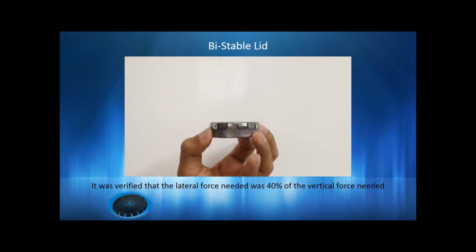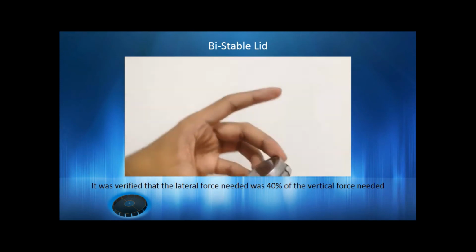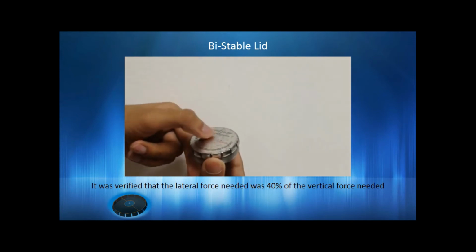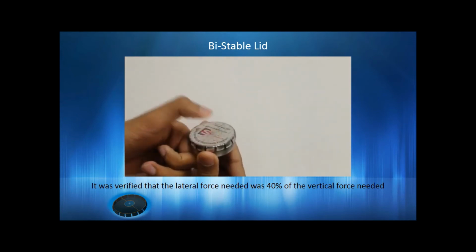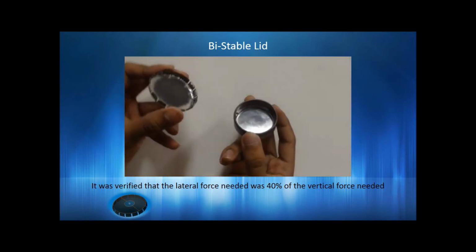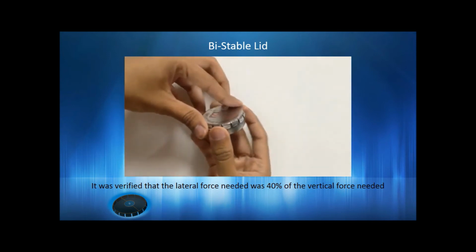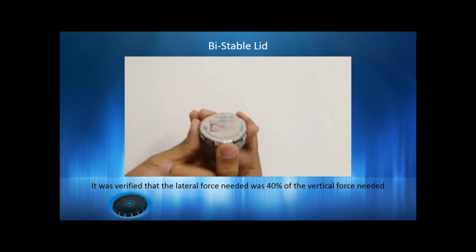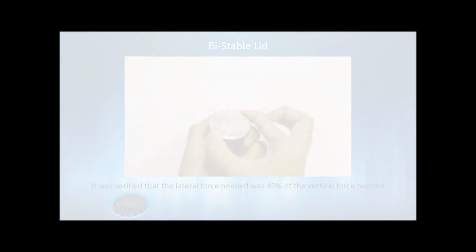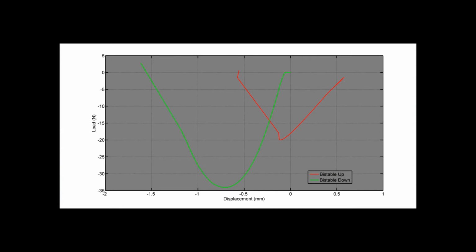This is a container which is available at the Indian Institute of Science, Bangalore. The lid of the container is bistable in nature. When pressed from the top, the side teeth displace outward, thereby allowing the container to be opened. The lid is now in its second equilibrium state. To close the container, the teeth are laterally pressed, which brings the lid back to its first equilibrium state. Interestingly, the lateral force needed was 40% of the vertical force needed for actuation.